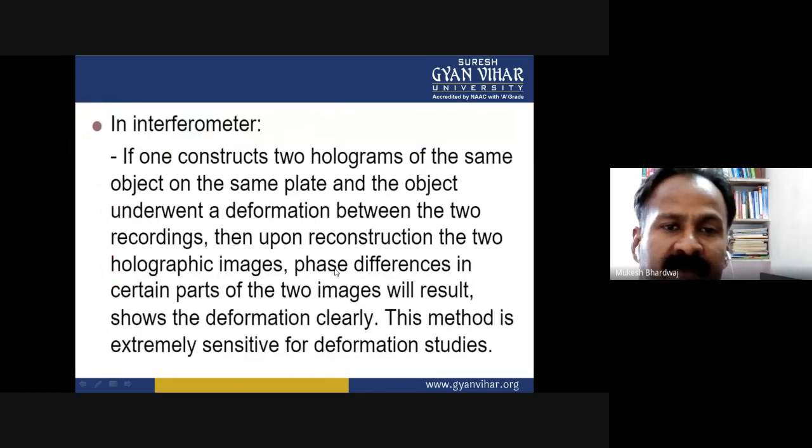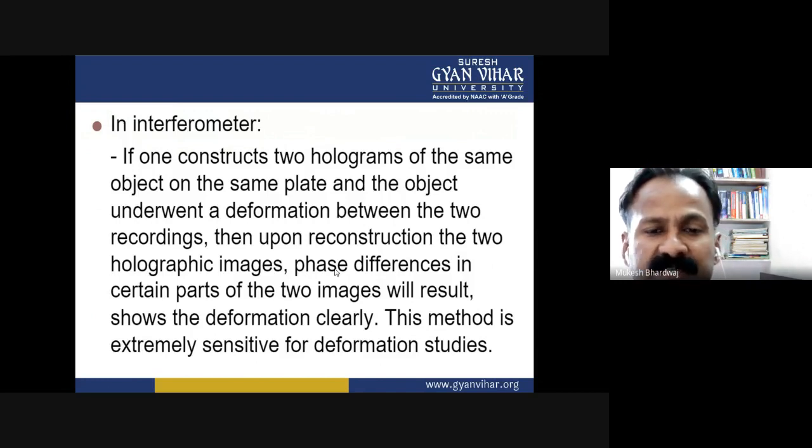In interferometry, if one constructs two holograms of the same object on the same plate, and the object underwent a deformation between the two recordings, then upon reconstruction, the two holographic images will show a phase difference in certain parts, which shows the deformation clearly. This method is extremely sensitive for deformation studies.